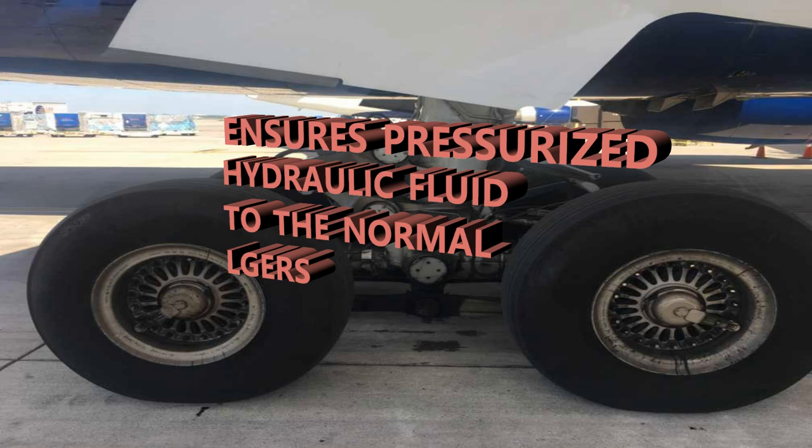All right, and then you have the LGCIS module that's going to make sure that that valve cannot be energized when the aircraft is in flight and on the ground during the takeoff and landing. And that's what isolation valves are for.